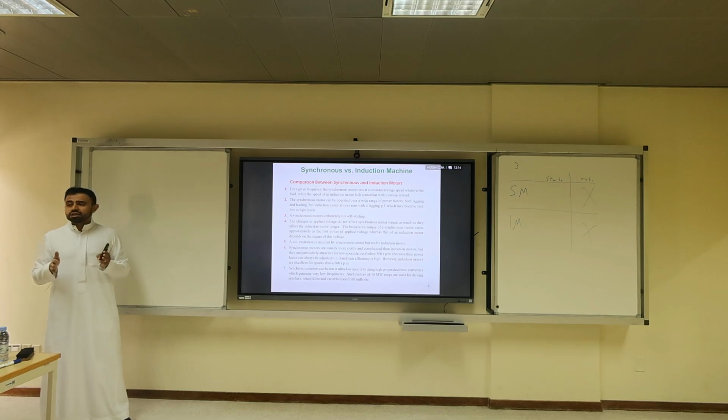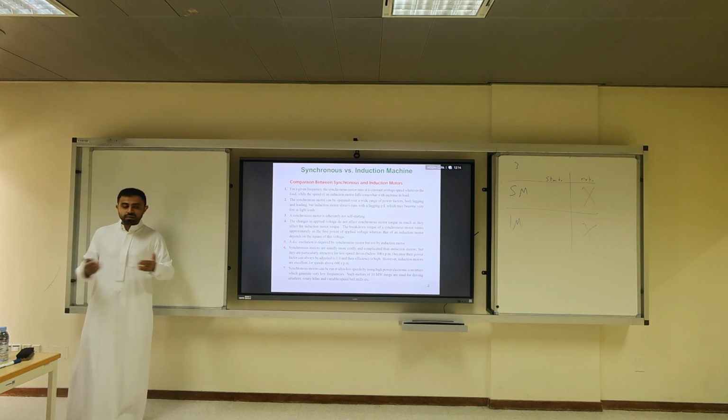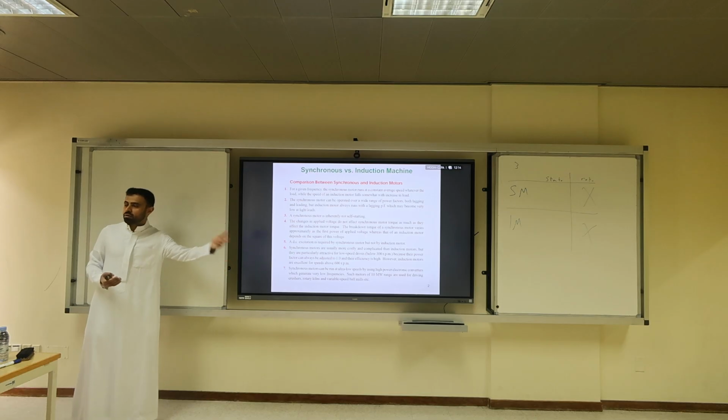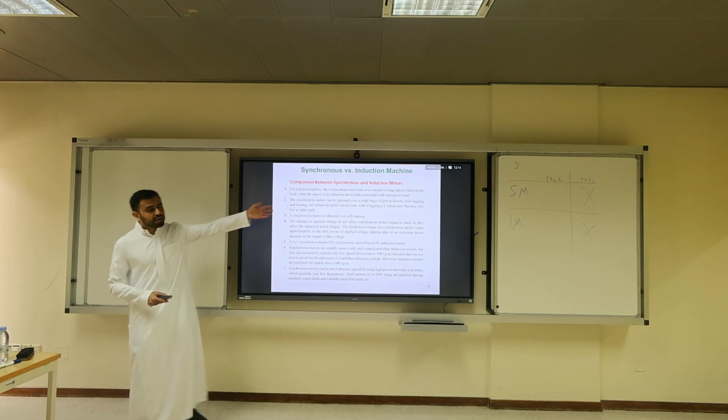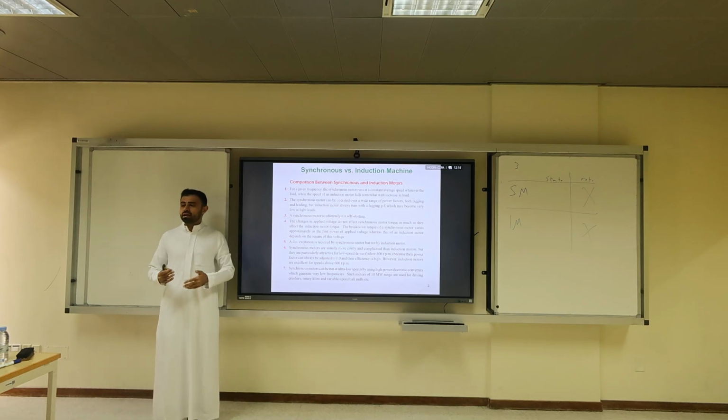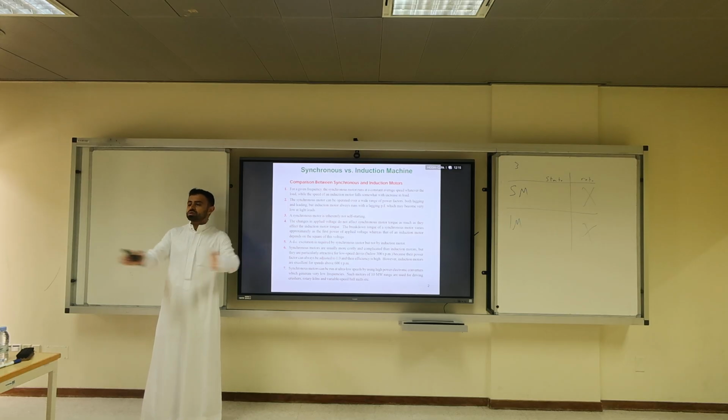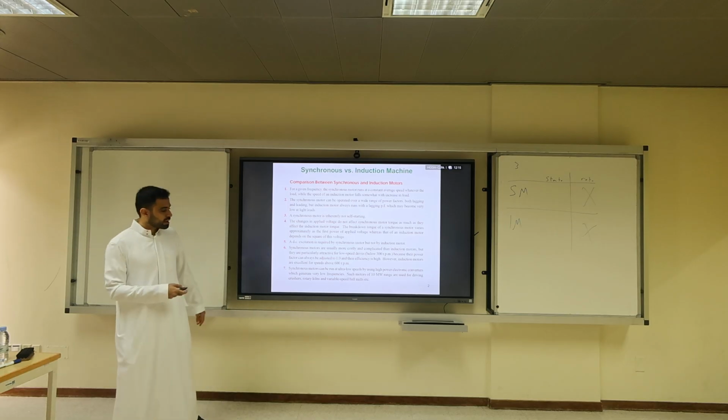What did I tell you about EVs? We have both induction and permanent magnet synchronous machines. In the same vehicle, you can have both. Maybe for front wheel drive you have induction, and for the back wheel maybe you have synchronous. You can have your own design. Okay? And the fact that they have the same stator makes the assembly line easier. Only when it comes to the rotor, you split the design. Remember, okay?